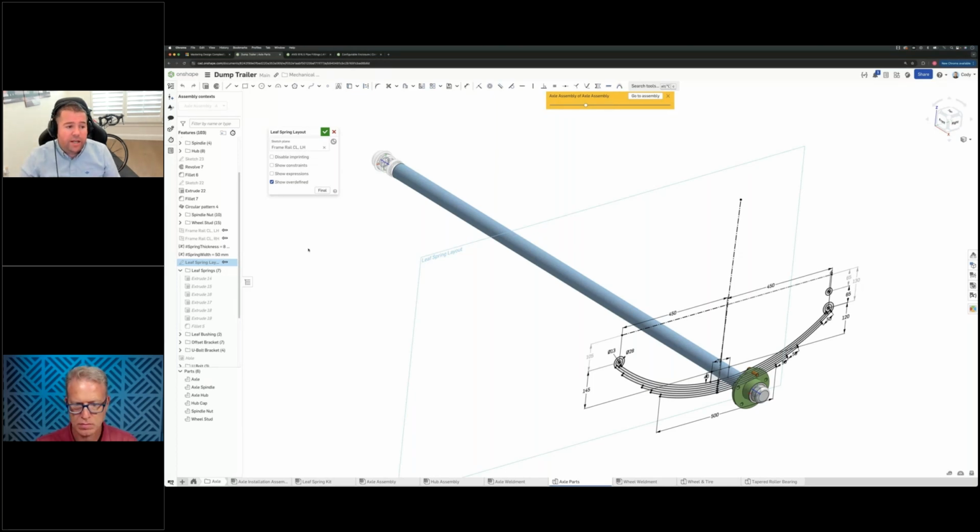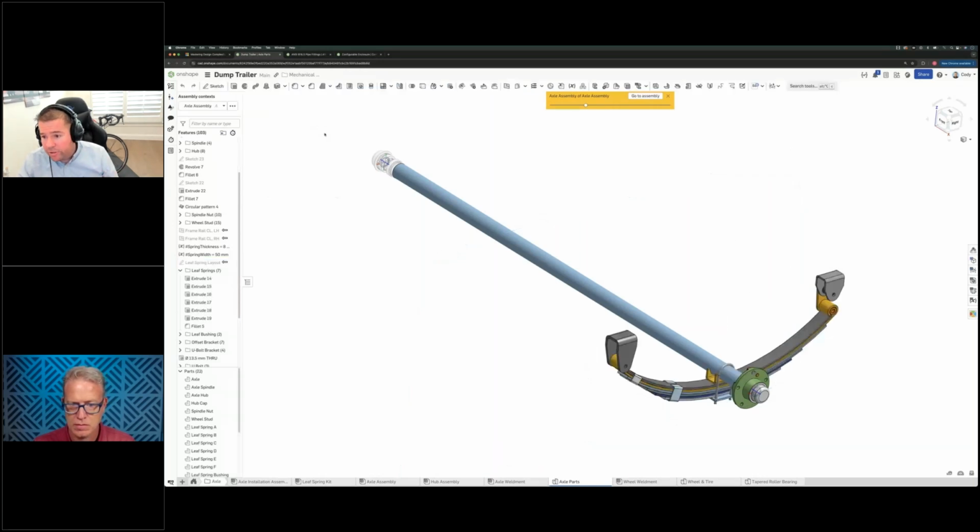And so this common technique of using layout sketches to drive overarching geometry, even the entire project in a lot of situations can be driven based on a single layout sketch, makes them extremely powerful. And also means that you have one place, and sometimes even one variable or one dimension that can have a dramatic change on dozens of parts, if you've built it in a certain way.